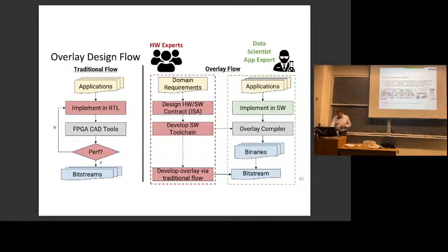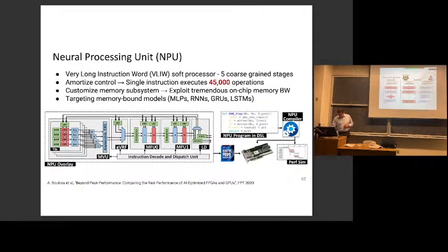One thing to watch for here is you could say, well, I could short circuit this. I'm just going to use Nios or MicroBlaze or RISC-V. I'll just use some conventional processor as my soft processor. You could do that. Your performance will be terrible, because you're paying the overhead of all of the instruction overhead and the muxing overhead and going to the register files that a processor has, and you're also paying all the overhead an FPGA has of making it out of programmable logic and routing. So it's not a very good solution.